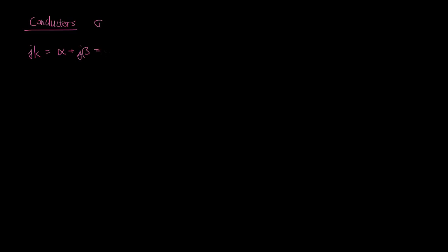And we had also previously discussed how that's equal to j omega square root of mu epsilon real part times the square root of 1 minus j sigma over omega epsilon. So if we were to rewrite this in terms of sigma instead of epsilon double prime.